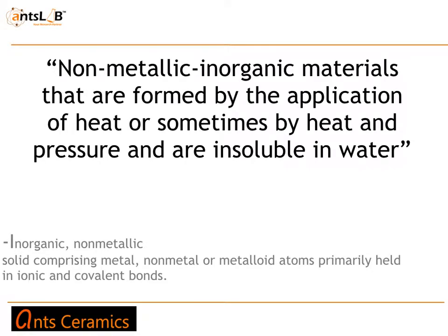In our last videos, we have seen many definitions of ceramics. Ceramics are non-metallic inorganic materials that are formed by application of heat and sometimes by heat and pressure, and are insoluble in water. So we can say that these are inorganic non-metallic solids comprising metals, nonmetals and metalloid atoms primarily held in ionic or covalent bonds.